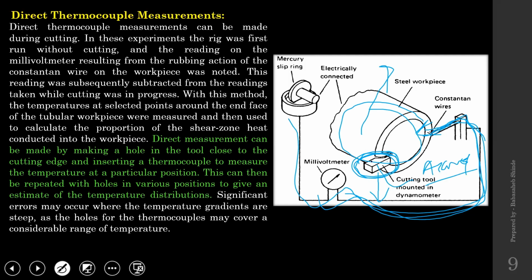So with a change in cutting tool or workpiece, this whole system need not be recalibrated again and again. For accuracy, we usually calibrate the system after a certain period of time, but that is usual practice. But when you change either workpiece or cutting tool, the system need not be recalibrated because the measurement system has not changed. Okay, that is the next advantage.